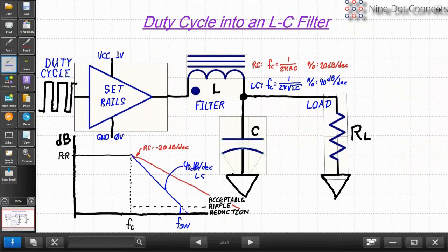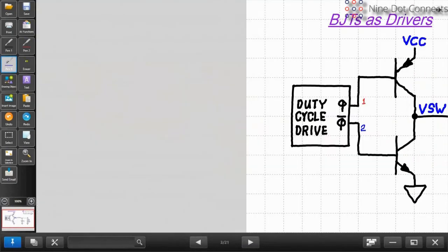So hence, we have something here that is taking a VCC and ground, some source voltage. In this case, we're assuming it's 1 volt, but it could be whatever. We're running it through a duty cycle, and we're coming out with a different voltage on the load. And that voltage on the load is controlled by the duty cycle. What we have here, in essence, is a buck converter.